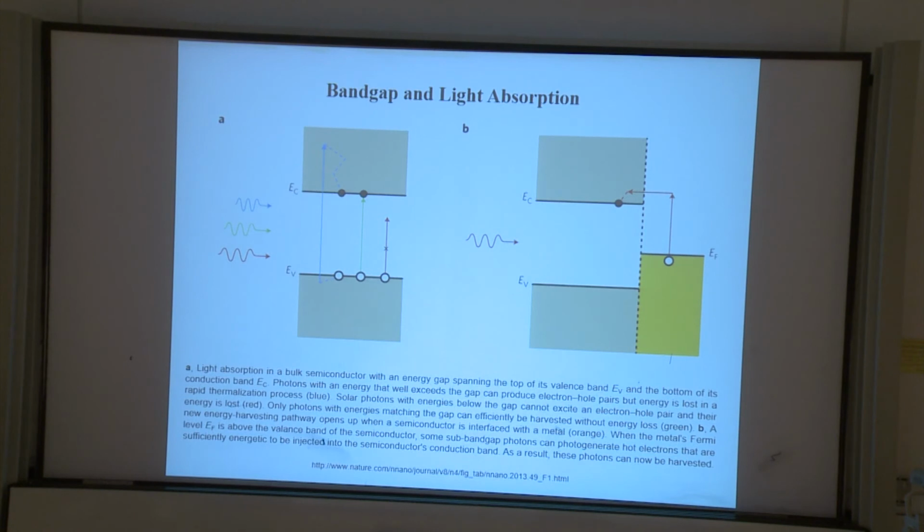Okay, so it will heat the semiconductor, and heating might not be a good thing. So actually, we cannot take advantage of this portion. So it's wasted. If you are using a photon with energy much higher than the band gap of the semiconductor, you are wasting your energy. Most of the energy is dissipated after the excitation of electrons in the conduction band.